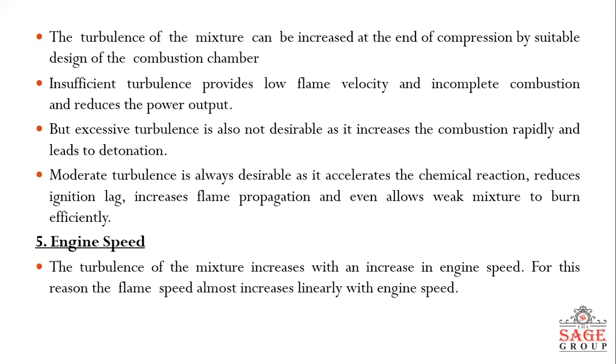The turbulence in the incoming mixture can be generated during the admission of fuel-air mixture through comparatively narrow section of intake pipe, valve opening, etc. in the suction stroke. Generally, turbulence increases the heat flow to cylinder wall. It also accelerates the chemical reaction by intimate mixing of fuel and oxygen.